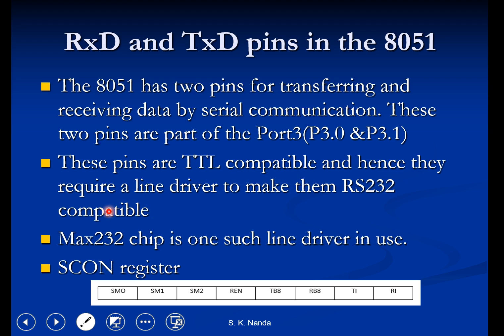So MAX232 is a specialized IC which offers an intermediate link between microcontroller and the PC. The transmitter of the IC will convert the TTL input level to RS-232 voltage standards. Meanwhile, the receiver of this IC will convert RS-232 input to 5 volt TTL logic levels.